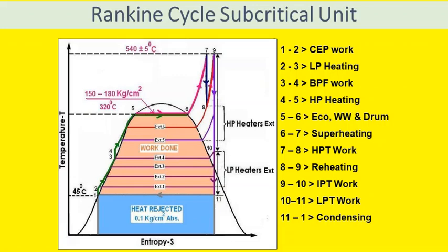Let us now review the modified Rankine cycle for the subcritical pressure regime of operation. In the actual vapor power cycle, the modified Rankine cycle adopted for a coal-fired thermal power station, the first process represents the work done by the condensate extraction pump.